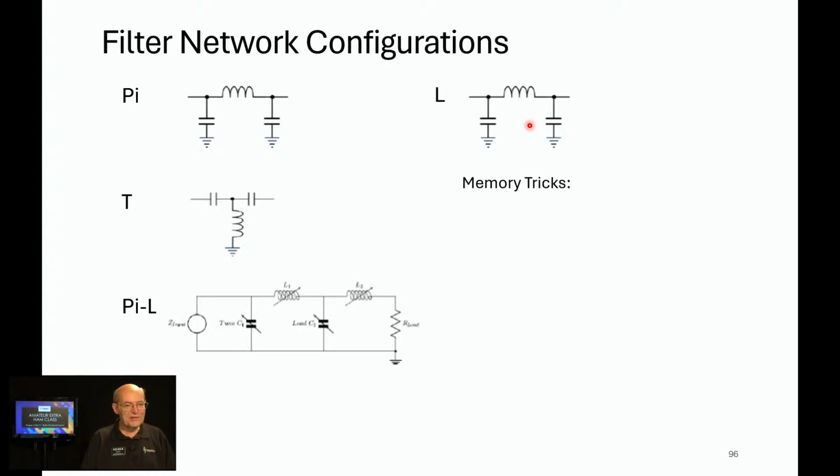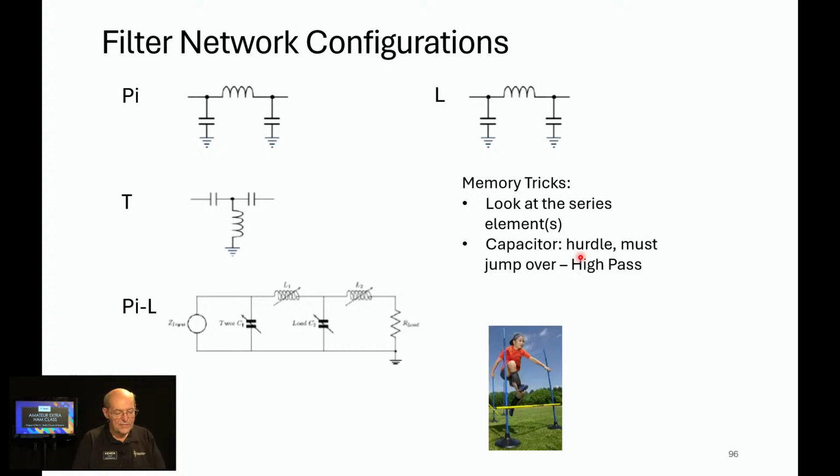So here's the memory tricks. I just thought this up this week. Kind of stupid, but it really helps remember which one is which. So first of all, look at the series element. The series element here is an inductor. The series element here is the capacitor. What I mean by series? Well, here's the transmitter, here's the load. We're going to have an inductor in series with the load. We're going to have capacitance in series with the load. So look at the series elements first.